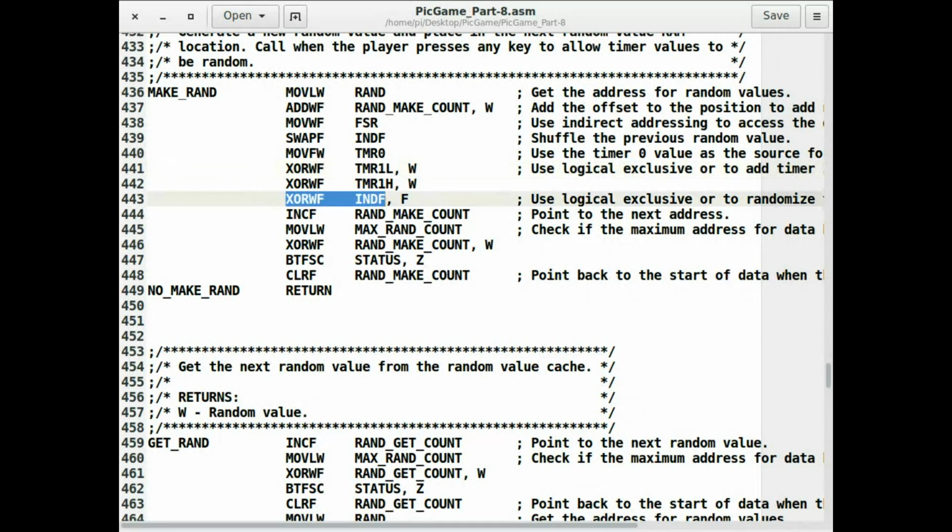And then I exclusive OR with what's in the current register, so the value that was first in there from initialization, I exclusive OR the value with. But next time round, after we've created 16 random values, it'll start over at address 0 again. So actually we'll also be exclusive ORing over the top of the previous values, and that also keeps it nice and random as well.